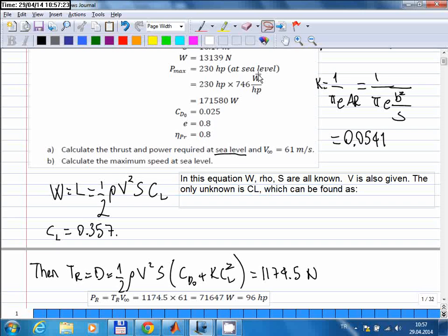So anyway, to account for that power lost to that, an efficiency factor is used. So you basically multiply the engine power with this factor. This is an approximation, obviously. This is not a constant number, and at different speeds, propellers have different efficiencies. But it is good enough to use a fixed number for propeller efficiency.